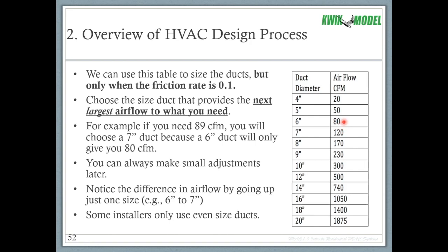In fact, the software is so precise that if it's 1 CFM more than a certain size duct will handle, it will go up to the next size. That's just how precise computers are by nature. Okay, if you need 81 CFM, it's going to round up to a 7-inch duct, which will give you 120. So there's some extra capacity there.